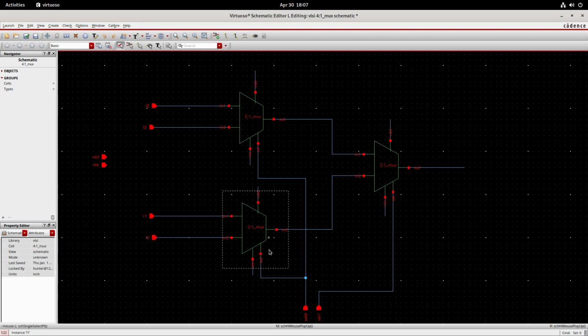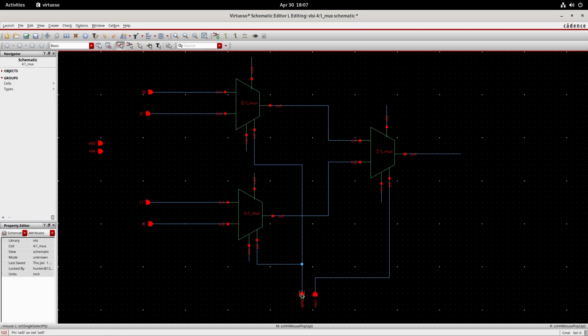Here is the reason. If you give a signal, for example 0, to this select line, 0 means the first input is allowed as an output. If this is 0, this input is getting an output here, and this input is getting an output here. Now here also if you give 0, the first input will be the output here, which means 0 0 means this input will go here and it will come outside.